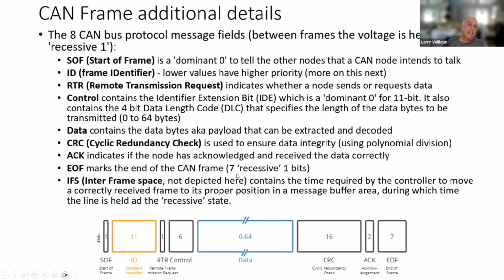I'm not going to get into all of it, because there's a lot of electrical characteristics related to CAN that engineers really don't need to know, unless you're actually building an ECU or engineering a CAN network for an automobile or truck or whatever it might be. One of those characteristics has to do with bit stuffing. So you don't get too many 1s or too many 0s in a row, because that holds the line at a certain level and can cause all the nodes to lose synchronization, because nodes synchronize through the rising and falling edges of each bit. If they don't rise or fall for some time, you're going to lose synchronization, because there is no central synchronization entity besides the data bit stream.